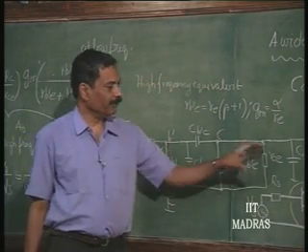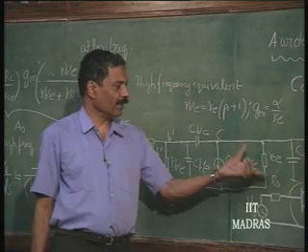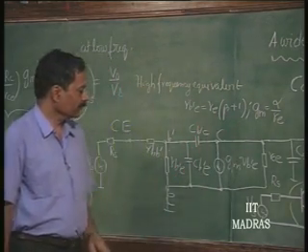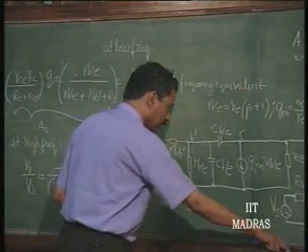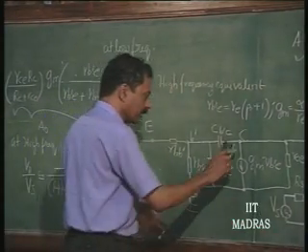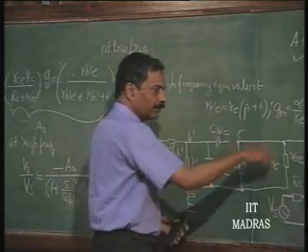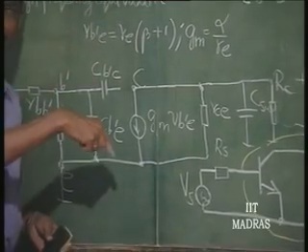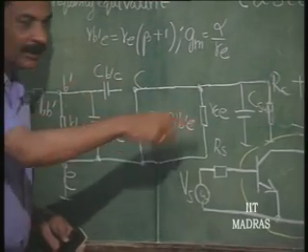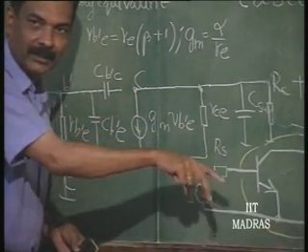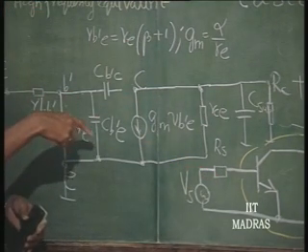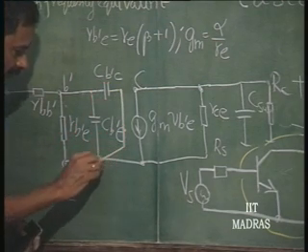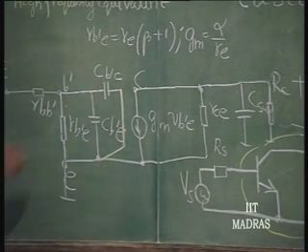So, C B dash C gets amplified by that factor 1 plus G m into R C parallel R C E. So, I can convert this capacitance, this is the approximation, even though at that point I am not considering the frequency dependence of the gain, but it is going to give me more capacitance than what is actually going to exist, because the gain is going to reduce anyway, right. So, I am actually overestimating the actual input capacitance. So, I am safe.